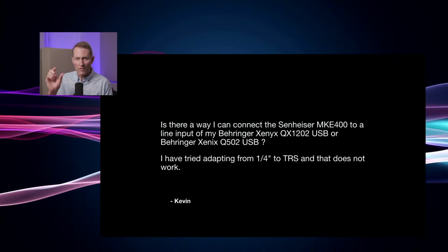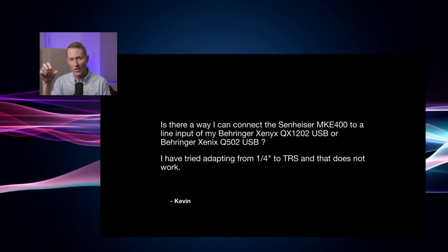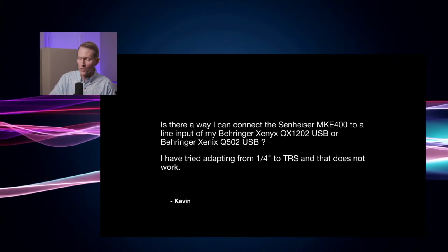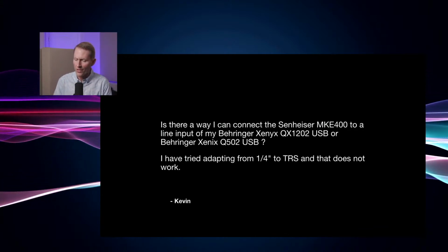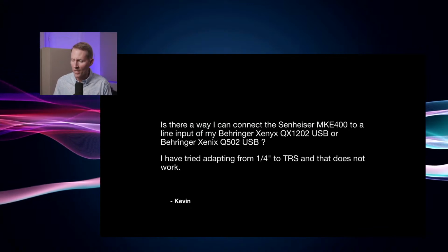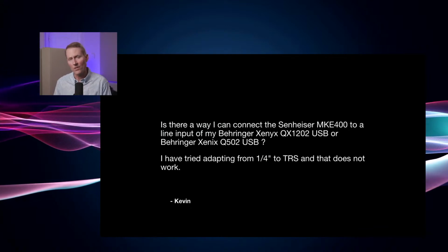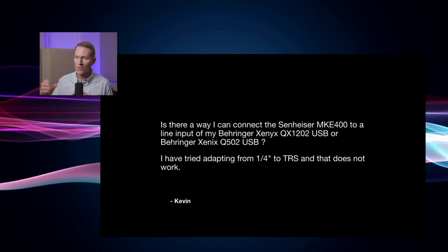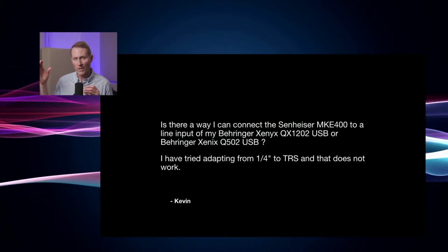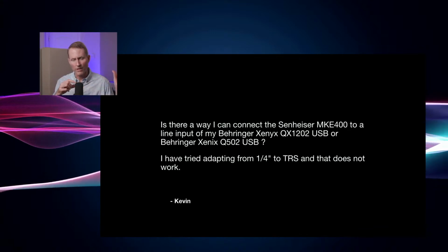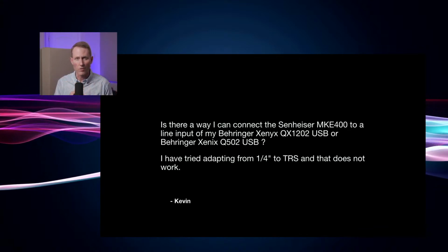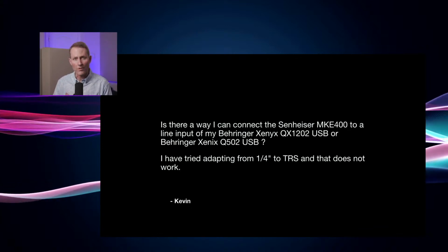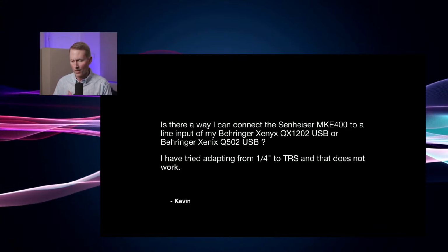So that's what the VXLR Plus and the VXLR Pro will take care of for you. In fact, I would suggest the VXLR Pro if you can, because that will actually convert the audio from the MKE400 to a balanced connection, which is what your Xenix is expecting. And it will also take the 48 volt phantom power from the mixer and convert that to 3 to 5 volts plug-in power, so you won't damage your microphone. So VXLR Pro or VXLR Plus should be your solution there, Kevin.